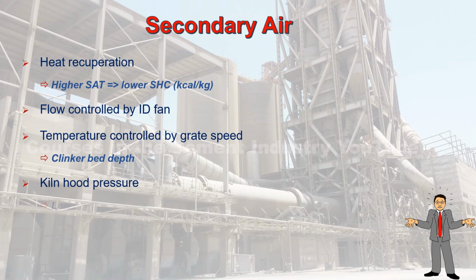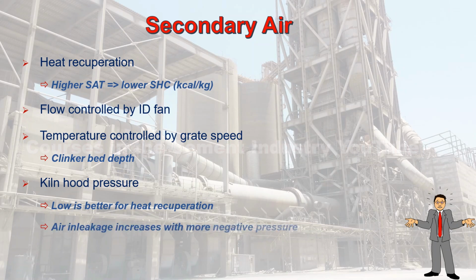4. Kiln pressure. 1. Low is better for heat recuperation. 2. Air in-leakage increases with more negative pressure.